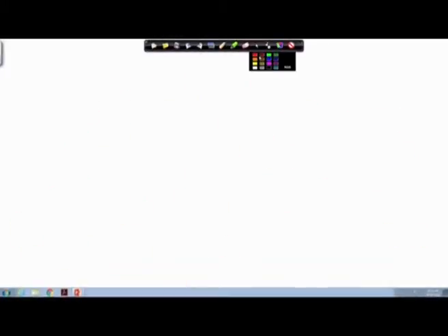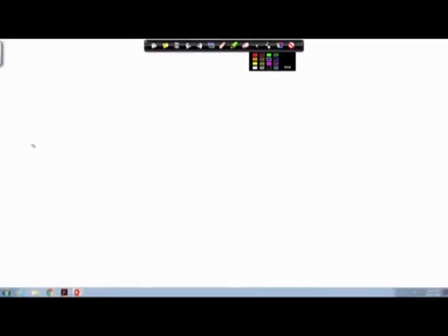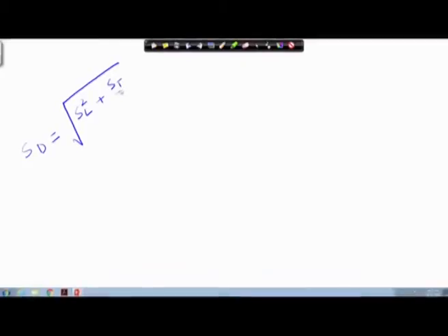What are the different parameters that we have to find out? First of all, we calculate the diagonal pitch, which is equal to the square root of SL square plus (ST by 2) whole square. This comes out to be 1.95 centimeter.